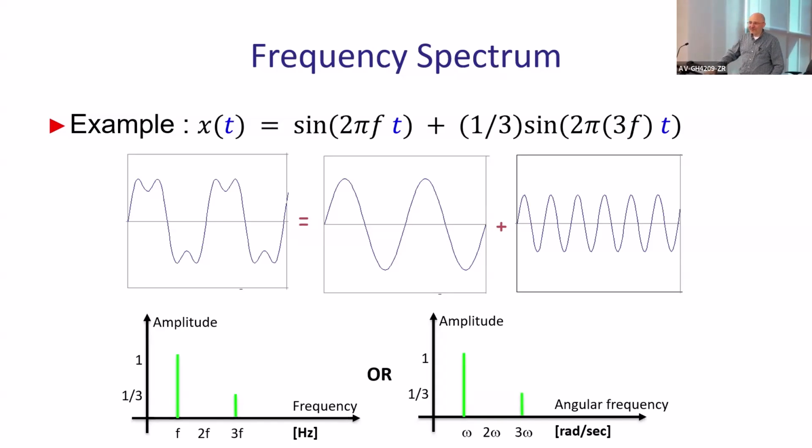Excuse me, I wonder why we just get amplitude at F and 3F and nothing in between. Because you have only two sinusoidal waves, which are the components of that particular signal, okay? If the signal looks much more complicated, typically you have a lot of different components, an infinite number of components for most signals. Like a rectangular signal includes all of the odd frequencies, a sum of sines to approximate a rectangular signal. And you'll have an infinite number of frequencies, obviously, in that signal.